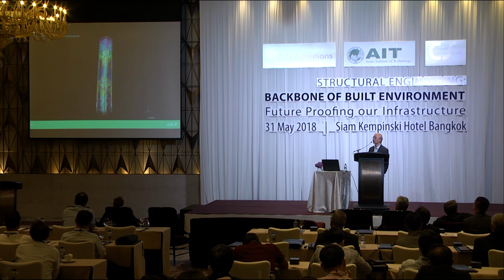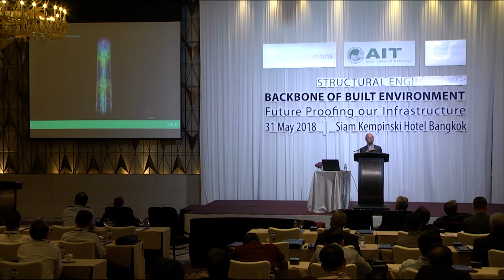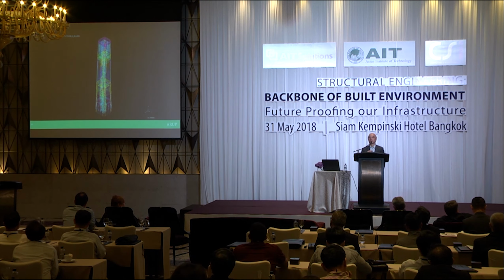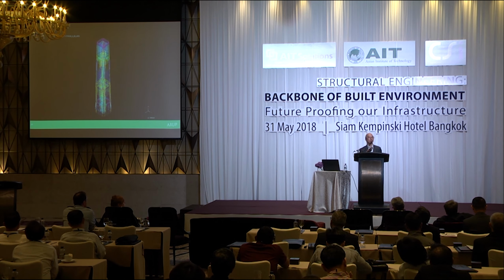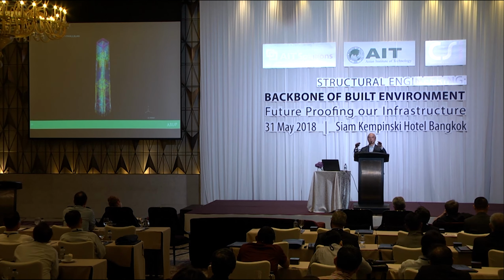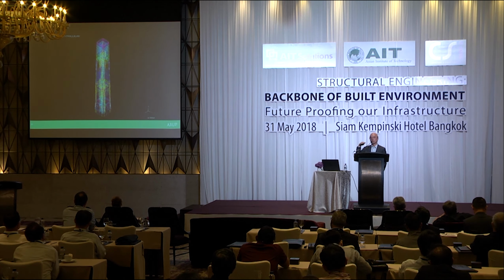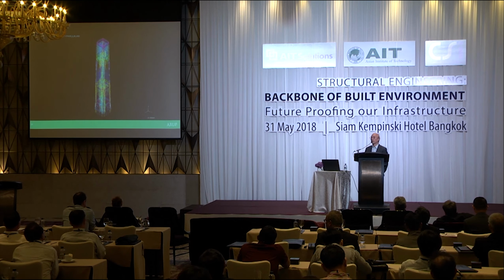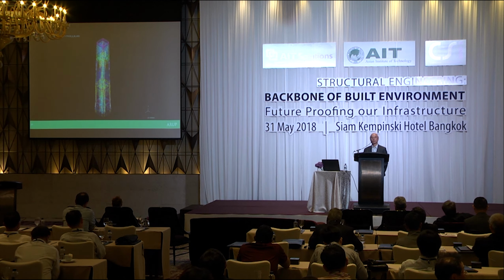If you look at the base carefully, the actual ground is moving, because we are using a displacement time history rather than an acceleration time history, which normal commercial computer software will do. There are other reasons, and because we have a podium and so forth, we want to check the displacement. At the same time, the earthquake actually also comes from horizontal movement, so we calculate the high modes and so forth.